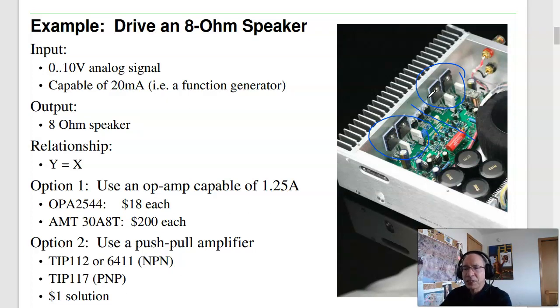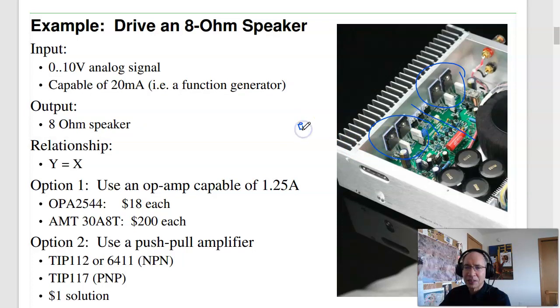That also lets you tell the difference between analog and digital transistors. Analog transistors have a big heat sink, or are designed for a heat sink. Digital transistors aren't necessarily designed for that. You can use analog transistors as switches. They're not designed for it, but they work perfectly well for that. The digital transistors, the little bitty ones that look like this, they're not designed to dissipate heat. You really don't want to use those for analog.